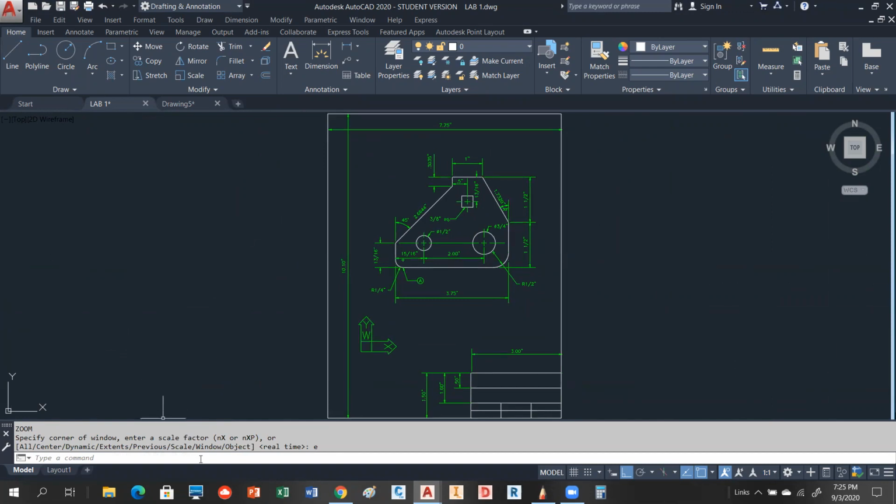So here's another one that's really neat, the window. Basically you're going to pick 2 points like that. And the size of the window will determine the magnification. So that's not going to be very magnified. This would be highly magnified, okay? The one thing about the zoom window is that you can only zoom in, you can't zoom out, okay? But you can keep zooming in.